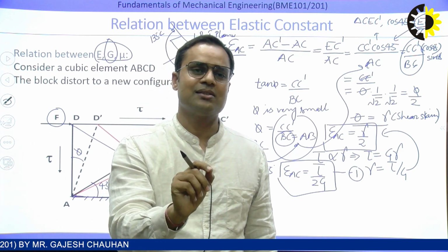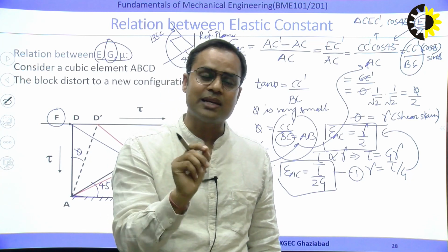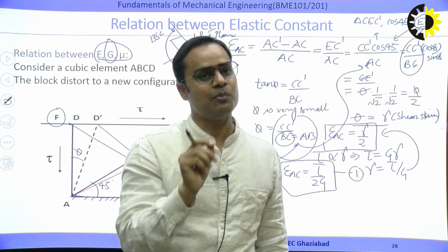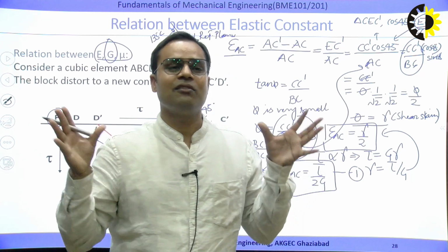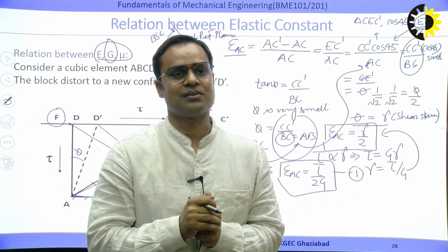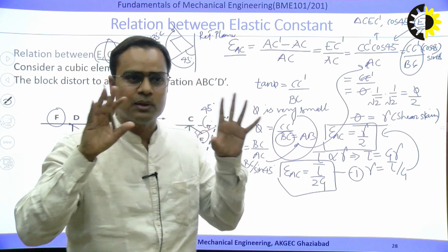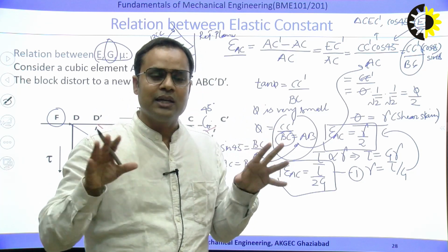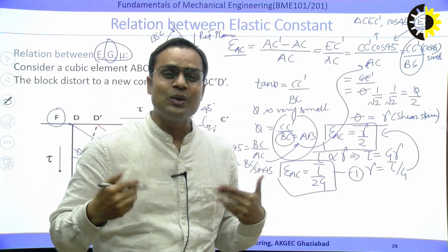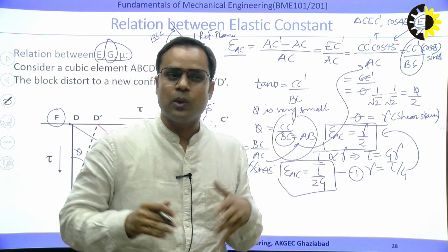One plane has tensile stress, and another plane has compressive stress. And the magnitude of these stresses is equal to the value of shear stress. It can also be proved. So I am not interested here to develop the relation for the pure shear case. I am only interested to know how much stress is induced in diagonal AC and how much stress is induced along the diagonal BD.